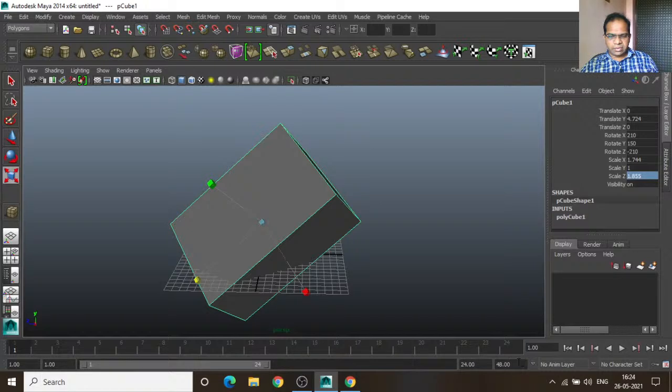and these boxes are for giving the values for frames. Whatever frames we want to take, we can enter those values in here. Okay, here it shows 48, but in the time range slider we are only able to watch 24 frames. Why? Because the time range slider is restricted to 24 frames, even though it has 48 frames inside. If you want to see all the frames, just move this one till the end. The range slider is moving till the end. We can have 48 frames. That means the total frames in this time slider is 1 to 48 frames.